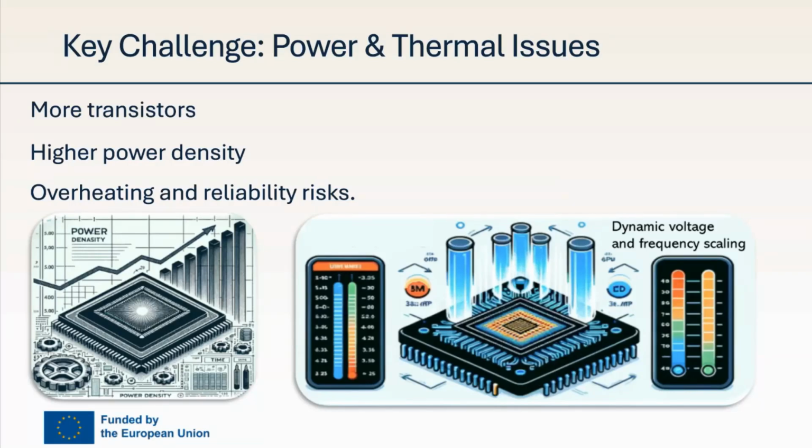This not only affects the performance, but also reduces the chip's reliability, as prolonged high temperature accelerates component degradation. Traditional methods like DVFS, dynamic voltage and frequency scaling, are typically not enough to handle this challenge, especially for high performance designs, necessitating advanced thermal management techniques.